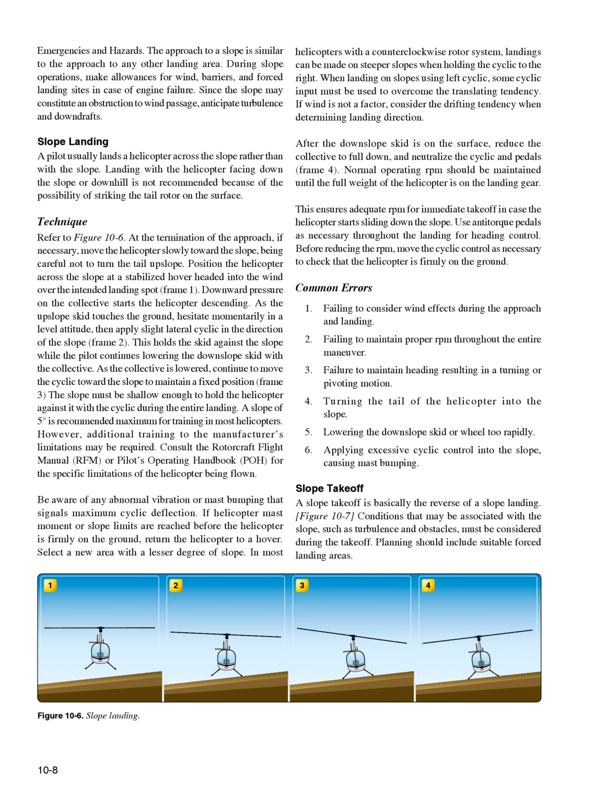Slope landing. A pilot usually lands a helicopter across the slope rather than with the slope. Landing with the helicopter facing down the slope or downhill is not recommended because of the possibility of striking the tail rotor on the surface. Technique: refer to Figure 10.6.